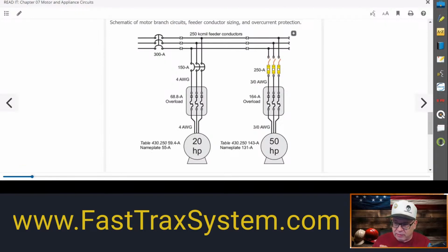And we got multiple motors here. As long as you can understand the basic concepts, overloads, as long as you realize that for the most part, most of the motor overloads are going to be dealing purely with 430.32. If you know how to do the pieces, then everything else you can just learn and add to it, right?